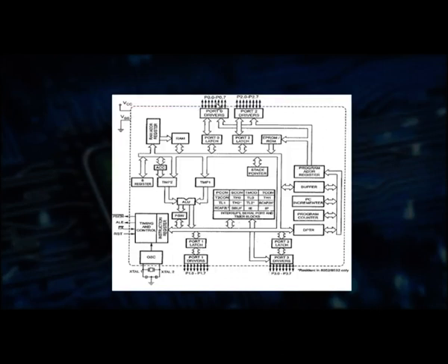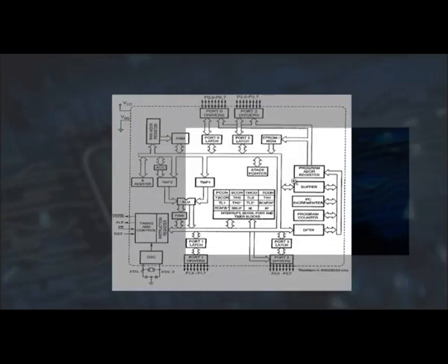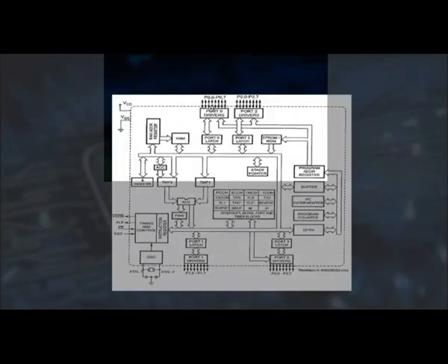So, 2 separate lines will be available, which are P3.0 and P3.1. The remaining 2 signals are the interrupt signals INT0 and INT1, which are external interrupts. So, on any response raised from the external devices, the microcontroller immediately suspends its current work and switches over to the specified task for completing the application. That is why we are using the 2 external interrupt signals.